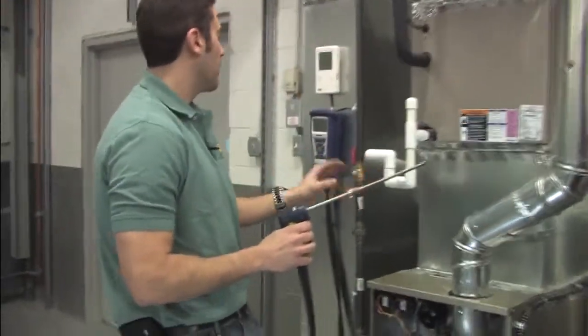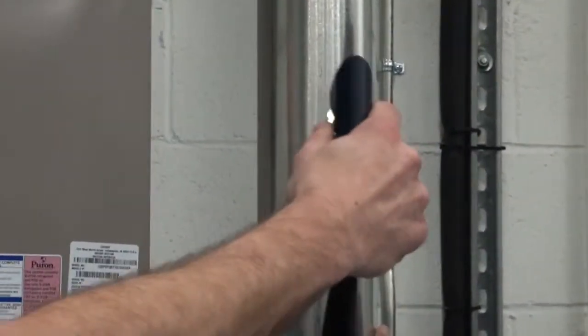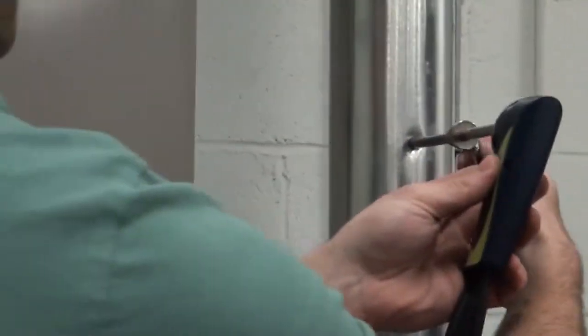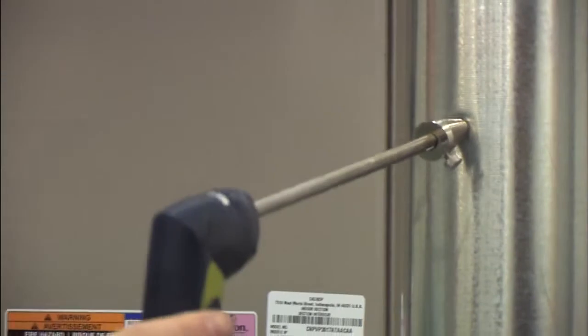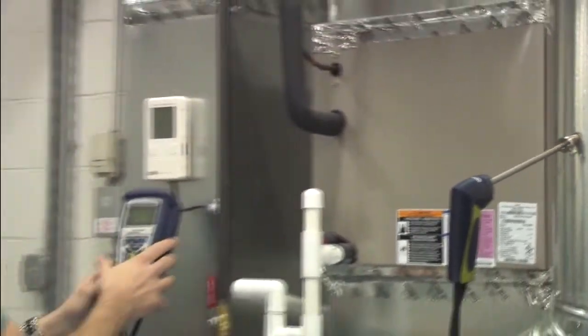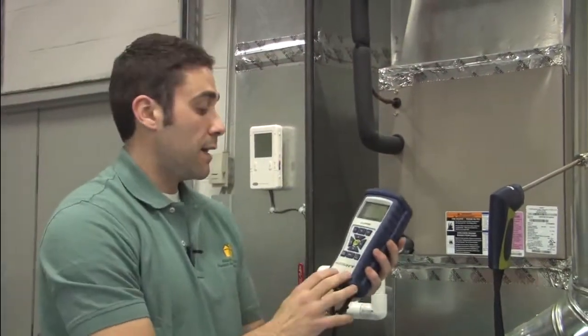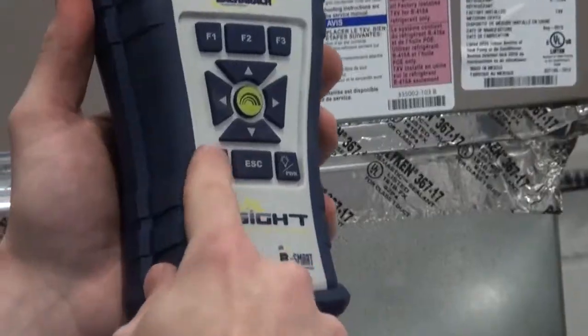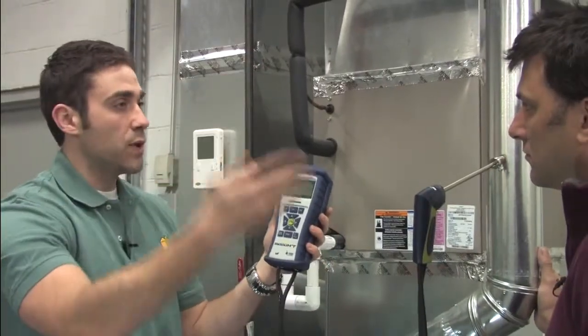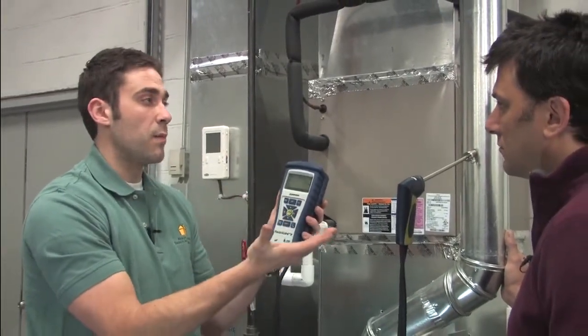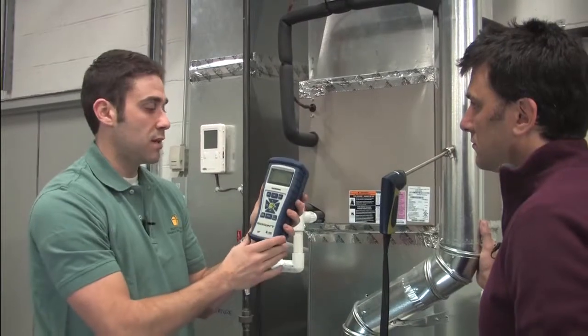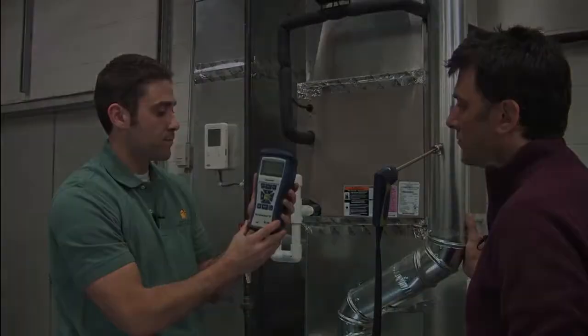So we'll drill a hole and then we'll put our analyzer in. The analyzer goes in about halfway. We have a little depth gauge we can adjust to make sure that it stays in there about halfway. And then we can go ahead and turn on our analyzer. We'll hit the run/hold button, which will turn on the pump. Now as the system's running, we start pulling flue gases in and we're analyzing them with the analyzer, testing to see what byproducts we have left over after the combustion process.